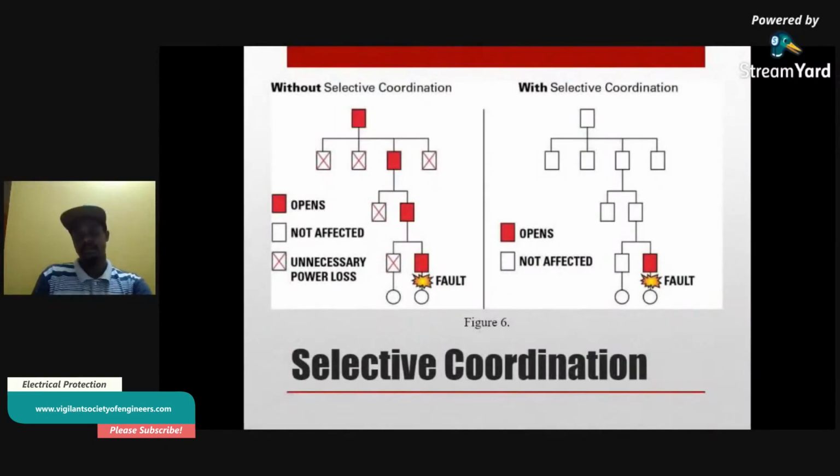All right, now a protection device, though it has the purpose of protecting conductors, must be so arranged in a way that prevents haphazard situations. So overcurrent protection devices should be selectively coordinated, which means you want to put the protection where it's deemed necessary.